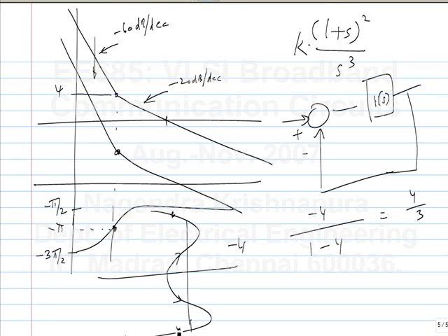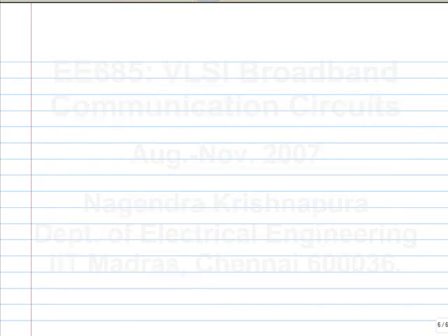The ultimate test of stability is whether the poles are in the right or left half plane. It's hard to evaluate, especially when you don't know the analytical description of the system. That's why we have these other approximate criteria which you can evaluate from simulation, like the magnitude plot or the phase plot. For analyzing the PLL, it's enough to know this one approximate criterion: if the slope of the magnitude response is minus 20 dB per decade at the unity gain crossing, then it is a stable system. Okay. Is that okay?